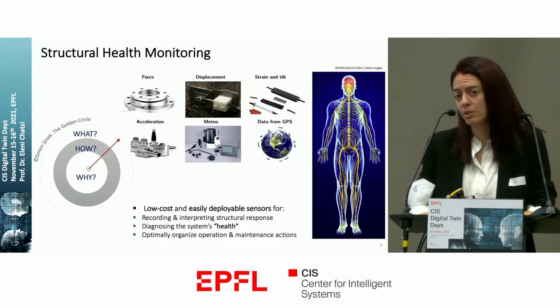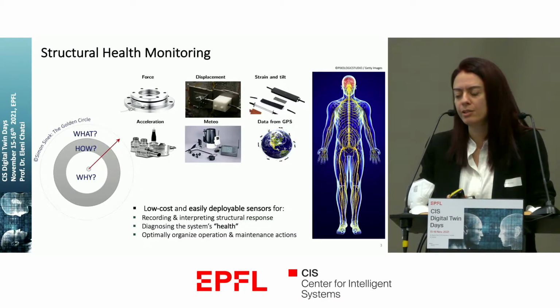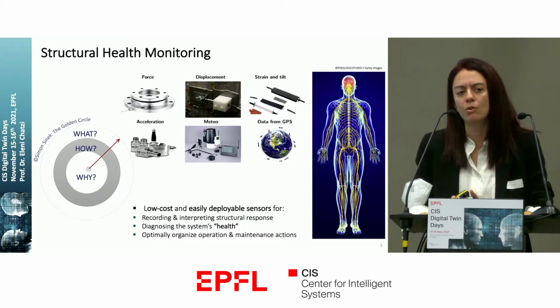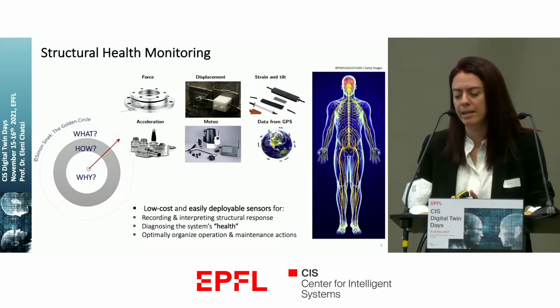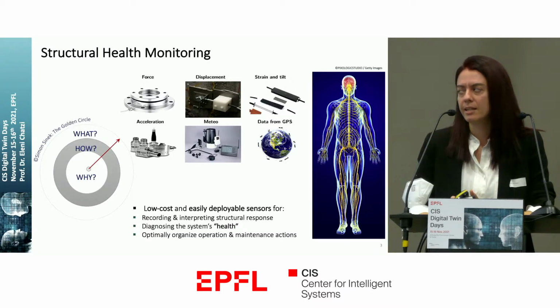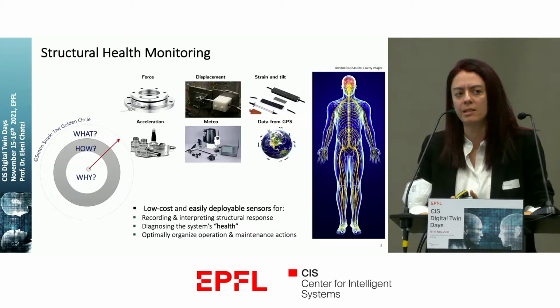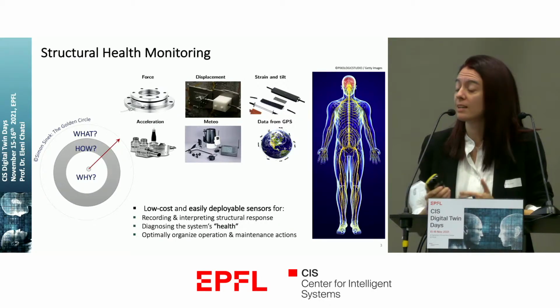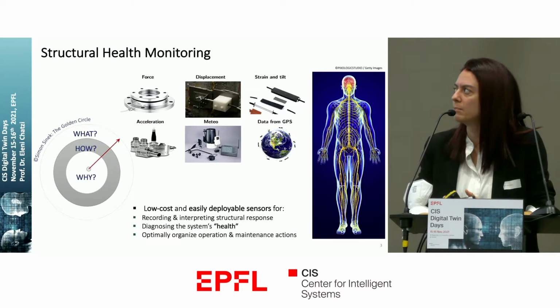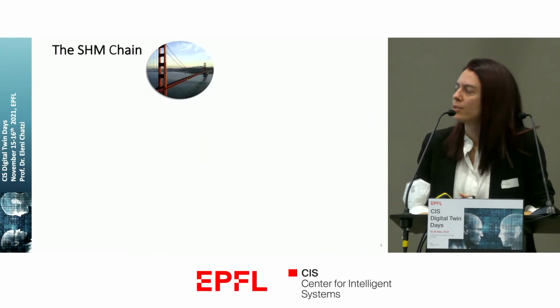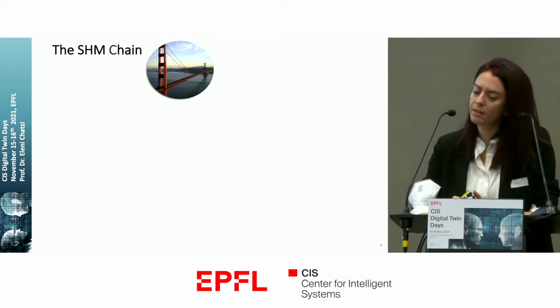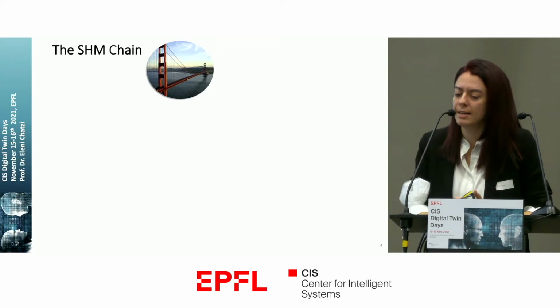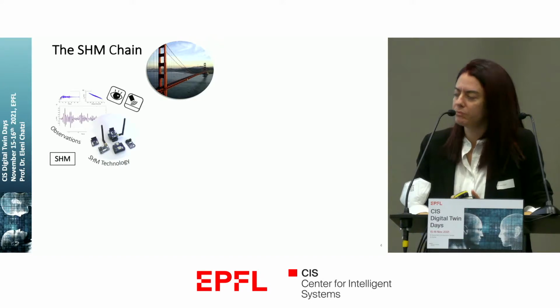And structural health monitoring is essentially the utilization of sensorics that is typically of low cost and that is deployed on structural systems for understanding behavior, for understanding the response of these systems, for diagnosing their current performance and condition, and for prognosing their remaining useful life and performance, allowing us to take decisions that could optimize their management. So this structural health monitoring chain, as I call it, is essentially one that comprises 4 main stages.